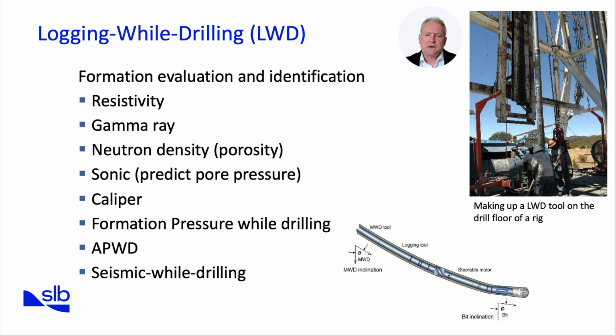APWD, or annular pressure while drilling, monitors pressure in the annulus and can be used to monitor hole cleaning efficiency and potentially give an early kick warning sign. Finally, seismic while drilling integrates LWD data with surface seismic, enabling formation mapping ahead of the bit while drilling exploration wells. This is often a tool used in deep water exploration wells.